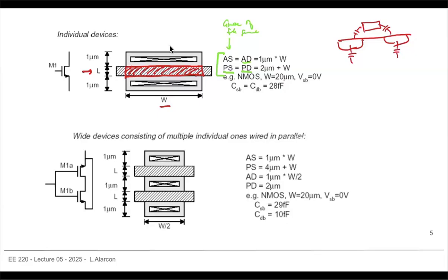Now, top view, this is sort of good, but this capacitance to the substrate also includes what we call sidewall capacitances. The capacitance on the edges is sort of the same, the same PN junction, but given the layout, it is a bit different.